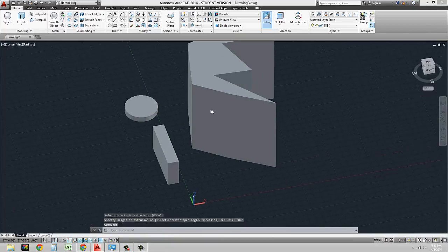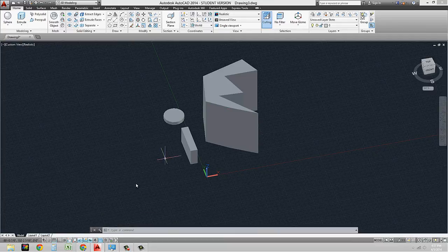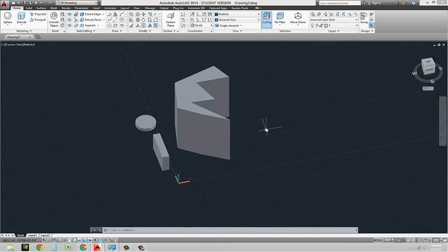What I find is that a lot of times for site models, AutoCAD tends to be very helpful, because it allows us to take these closed polylines and closed objects and extrude them to different heights. Additionally, there's also the press pull tool, which does the same thing, but it allows us to extrude regions without having a closed polyline. For this example, I'm going to draw a series of lines.